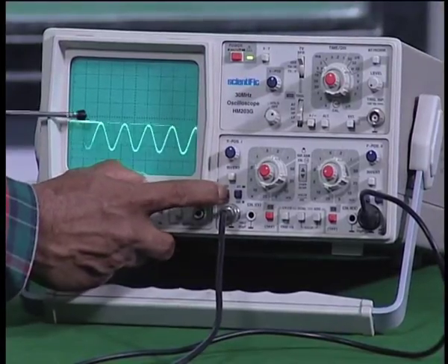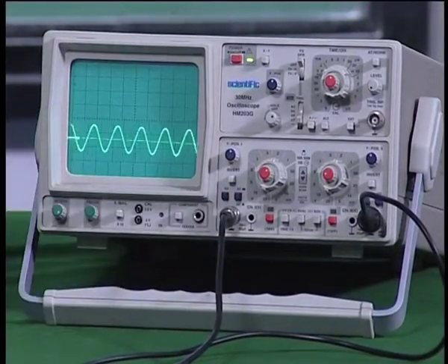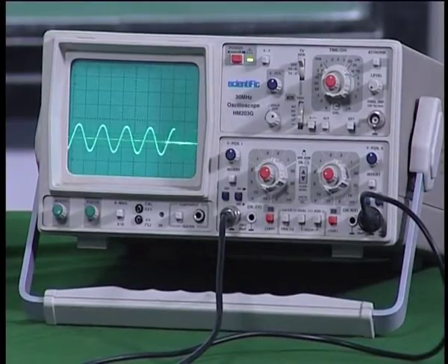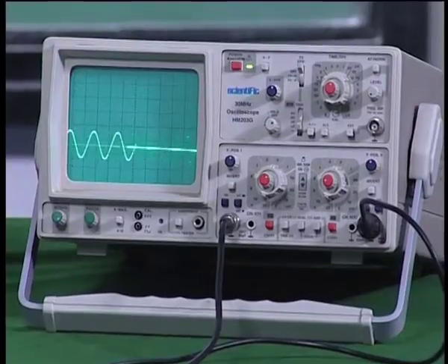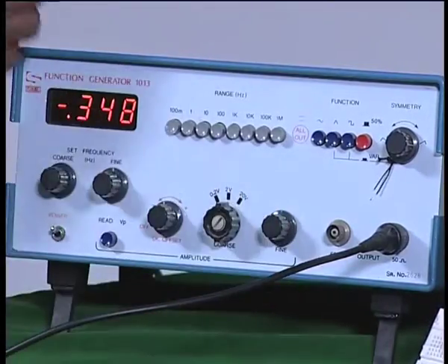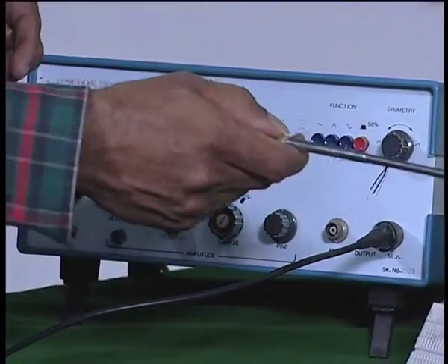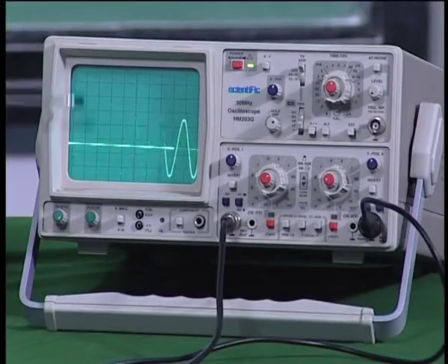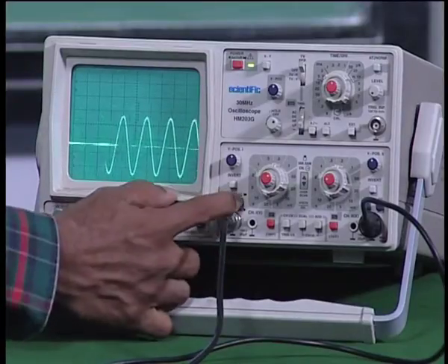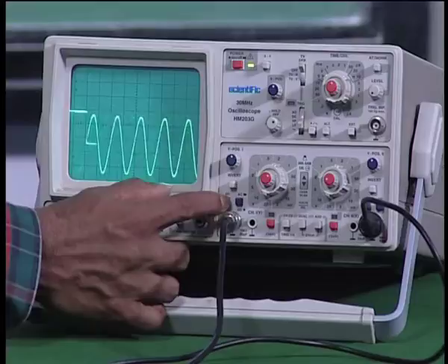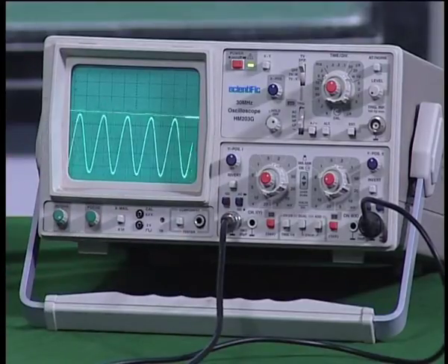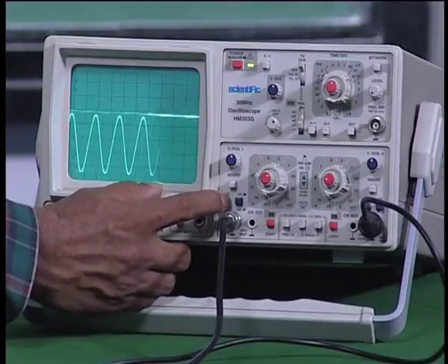So, when I put it into DC, it goes to the peak value. So, it has been charged to the peak value, and even if I increase the input amplitude by using the function generator, I am going to increase the amplitude now, and you would find at the output in the signal in the oscilloscope, again you see a magnified signal, and if I again make it peak detect, you can see it is going up to the corresponding peak now. So, it is indeed detecting the peak.